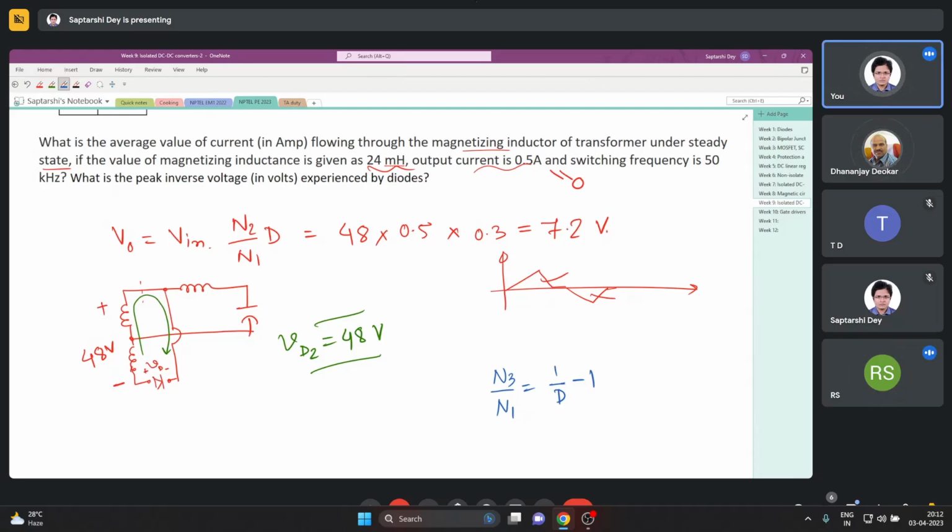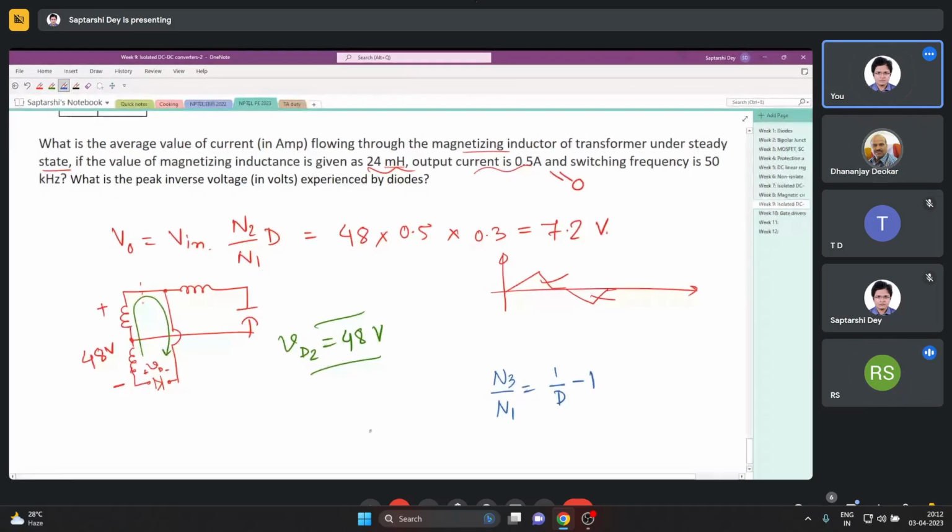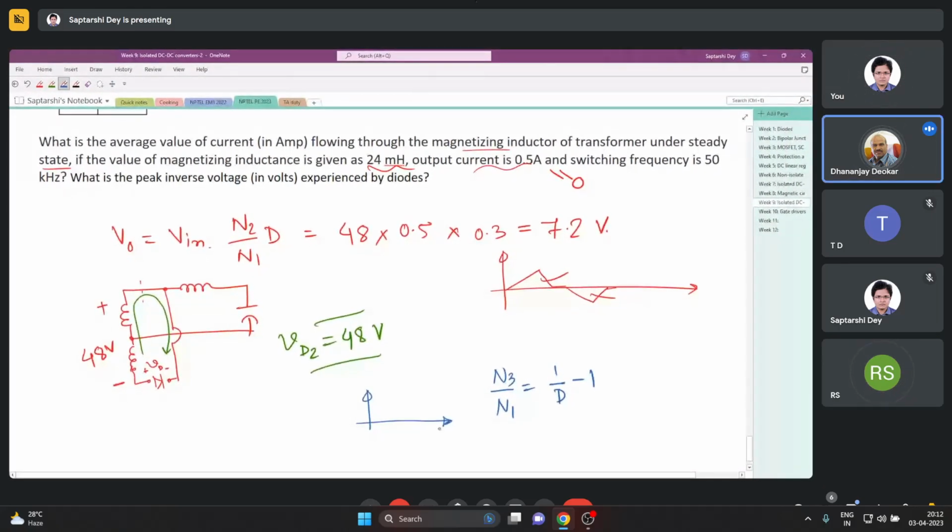But the thing is, since this is a kind of buck converter, forward is just an isolated buck converter, and I discussed this one day. We cannot go for very large boost or very large buck. Those gains are restricted. Yes, the circuit non-idealities start dominating beyond some ranges of D. I do not think people go for that.